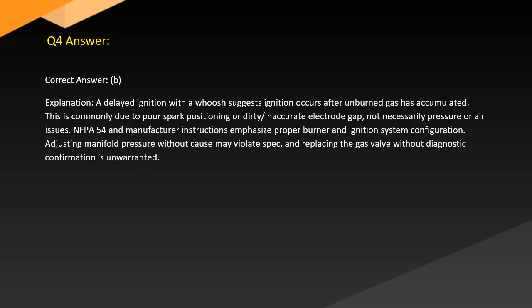Answer. Correct answer: B. Explanation. A delayed ignition with a whoosh suggests ignition occurs after unburned gas has accumulated. This is commonly due to poor spark positioning or inaccurate electrode gap, not necessarily pressure or air issues. NFPA 54 and manufacturer instructions emphasize proper burner and ignition system configuration. Adjusting manifold pressure without cause may violate spec, and replacing the gas valve without diagnostic confirmation is unwarranted.